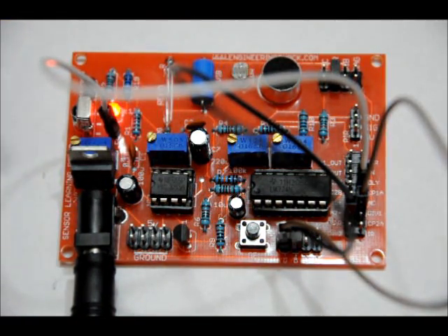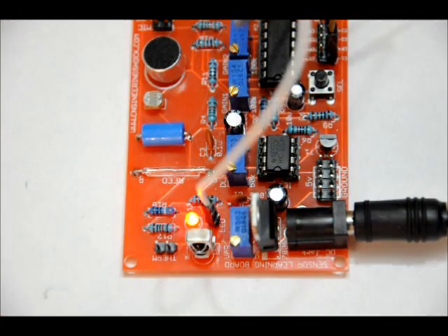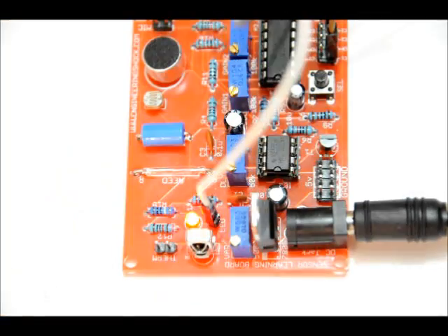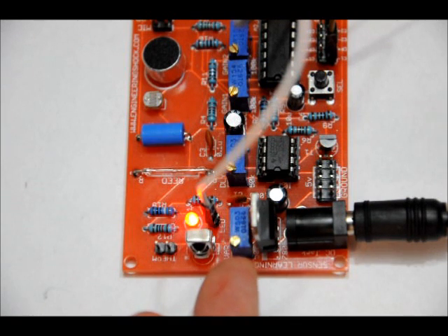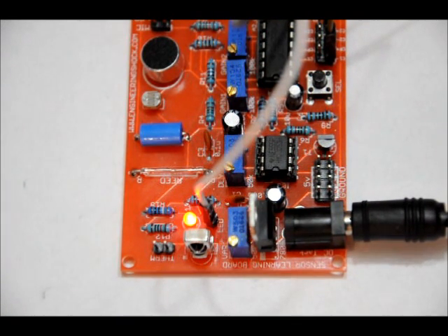As we can see, the output is normally high. So I'm going to turn this around so you can see the LED better. I'm going to start turning the lights on and off. So you can easily fine-tune this based on your environment by testing the voltage on the LDR on the div 1 pin, and using the comparator and the variable resistor set as a voltage reference to make this really sensitive.